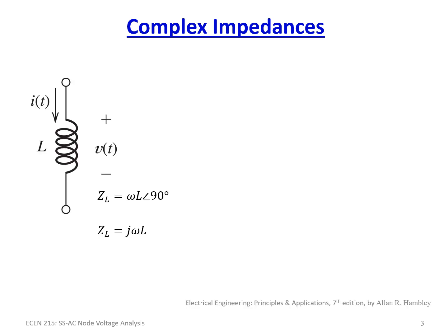So the impedance of an inductor, again just review from what we had before, is equal to omega L, where omega is the frequency in radians per second. And if you're given frequency f in hertz, like 60 hertz or 100 hertz, then omega is just 2 pi f. So take 2 pi times the frequency, and that gives you omega.